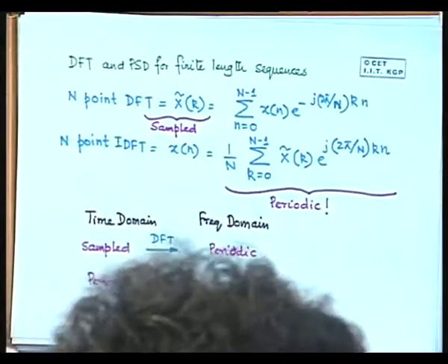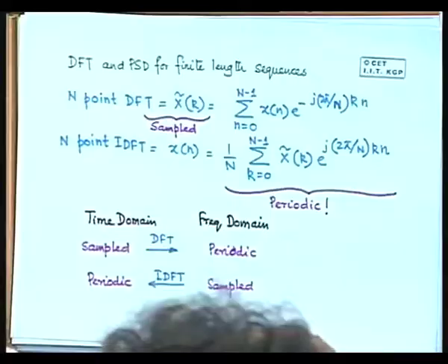So now we come back. So now we have got a fairly intuitive formula for calculating autocorrelation. Simple time average between samples which are L apart. Right? Very simple formula actually. That's what anybody would do. Now let us see how to calculate the power spectral density from this.